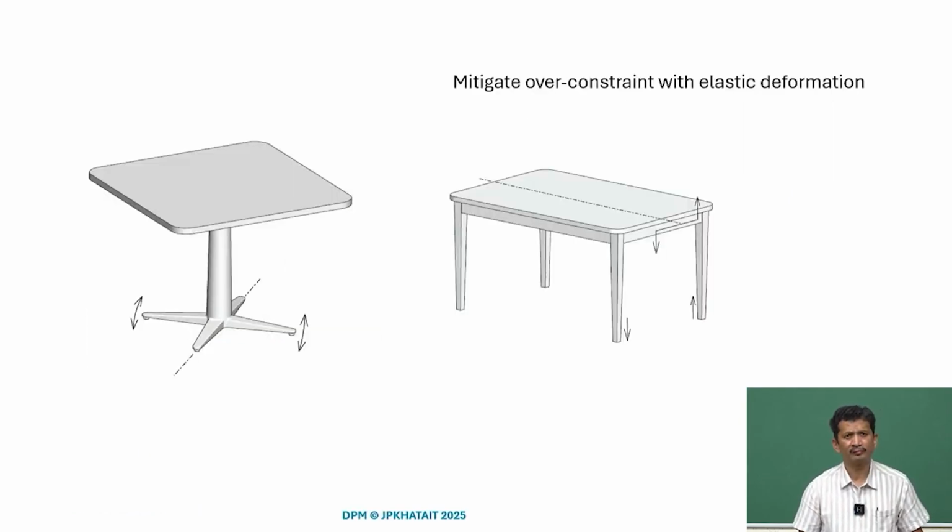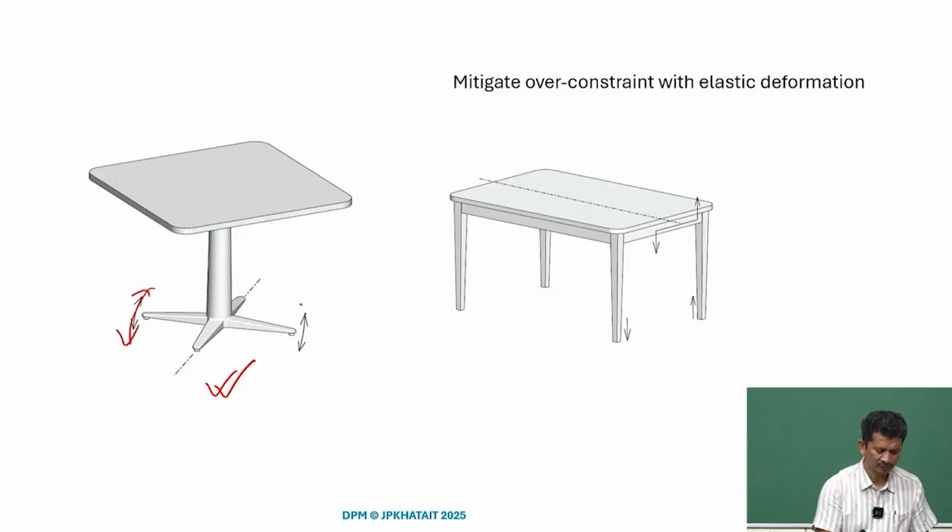What we also observe is that the four-legged table is not a stable solution. In this case, this pedestal has 4 supports, and yes, the exact constraint with the 3 points is valid if it's a rigid frame or rigid object. Here, if it's rigid and we have 4 points, we will have a problem and it will always rock, because we are now talking about 4 points.